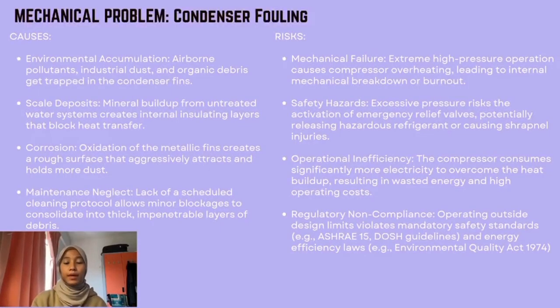Next, we have the mechanical problem. Fouling happens for several reasons. Firstly, we have environmental accumulation. Dust, pollutants, and debris get trapped in the condenser fins. And we have scale deposits. Mineral buildup from untreated water creates insulating layers inside. And then we have corrosion. Rough oxidized fins attract and hold even more dust. Lastly, we have maintenance neglect. Without regular cleaning, small blockages become thick, hard layers of debris.